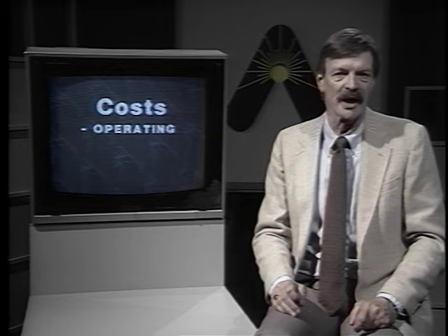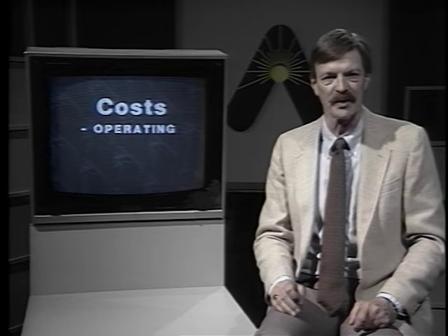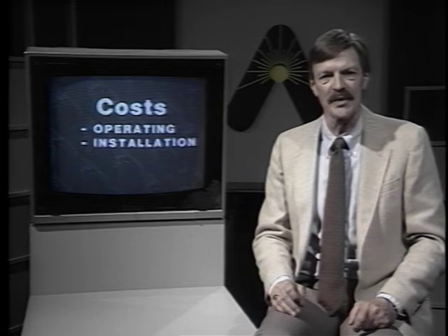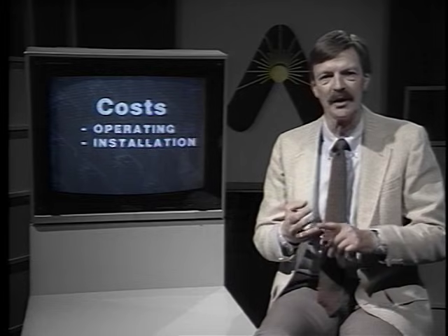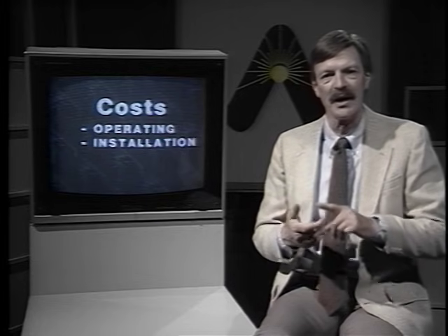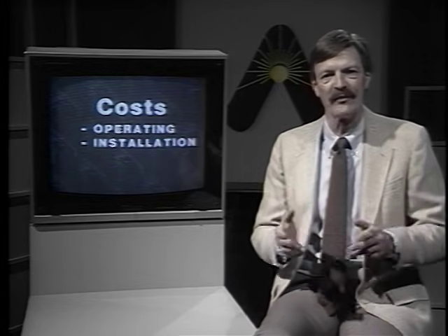The cost of humidification is our final consideration, the so-called bottom line. It is also one of the most complex, having several elements that must be looked at. The operating costs of any of these methods, if properly designed and installed, is low when compared to the accompanying comfort control system. The installation costs are dependent upon the availability of steam, hot water, electricity, compressed air, and makeup water at the humidification site.